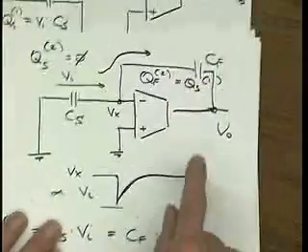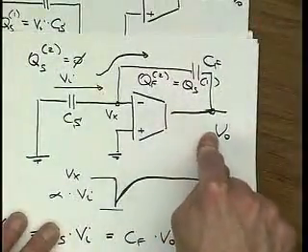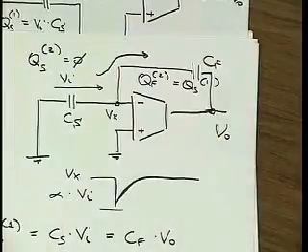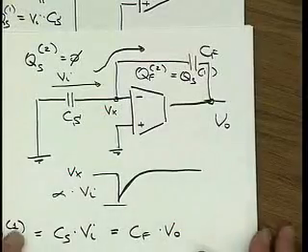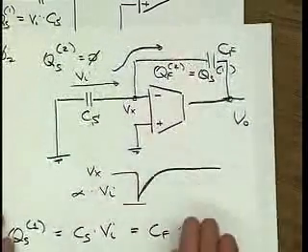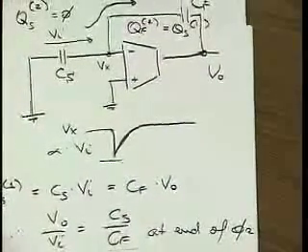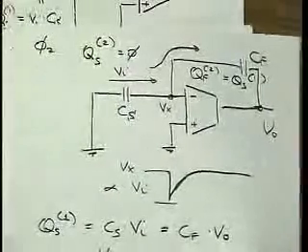Like, for example, with the switching scheme that we are using, during phase 1, the output is shorted, and it's 0, right? Okay. And during phase 2, it's going to go more or less slowly, depending on the speed of this amplifier, from 0 to that correct value. Well, we'll look at the simulation results to see that a little bit better.